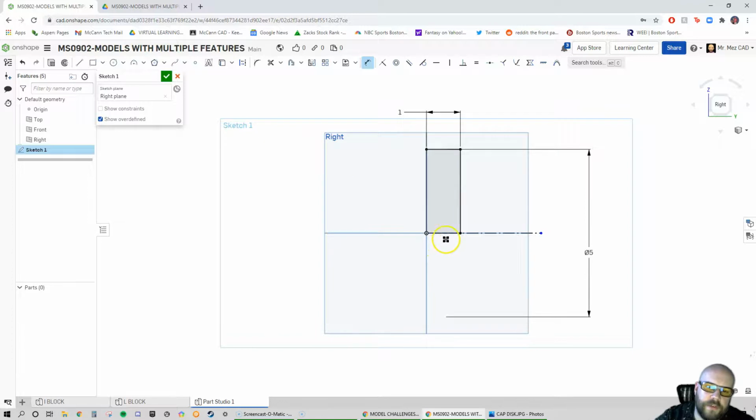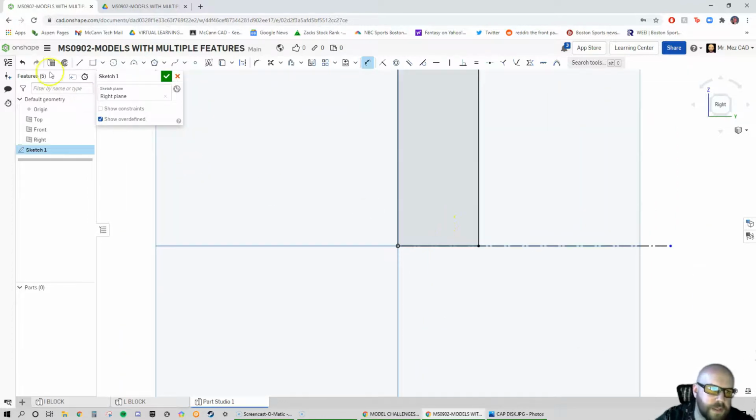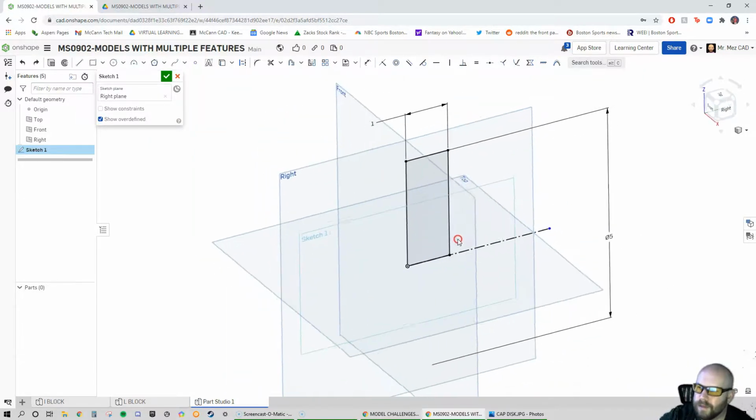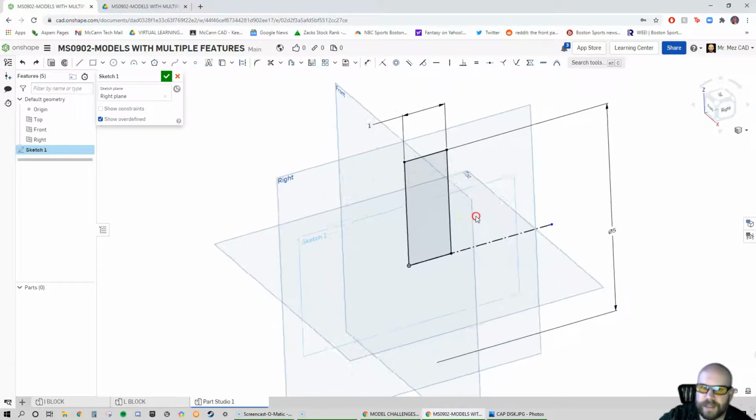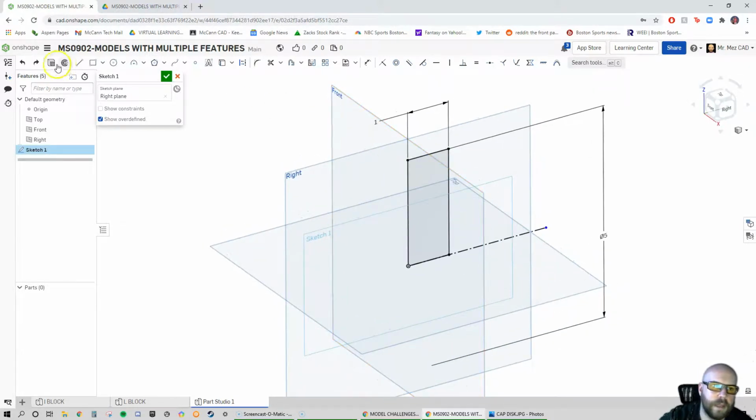Now, here's the advantage of this, if you're wondering why we would revolve this. If I down the road want to put in like a hole in here, all I've got to do is just put like a line like this. Maybe I got like a groove in here, kind of goes like this. And I put that in, I trim, and now I've got a hole in there with a snap ring groove. Okay? Simple change. If I extrude this, I have to create a completely new feature to do that. Yeah, it doesn't sound like a big deal, but down the road, you make some more advanced pieces, it becomes a problem. Okay? So now we're going to go up and pick revolve.